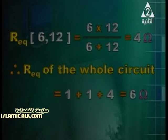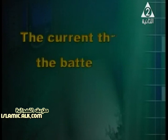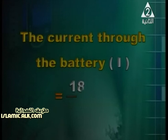And now we want to calculate the current through the battery. Current through the battery equals the battery 18 over the total resistance 6, it is 3 amperes. Potential difference across AB, across the first parallel group, is the current times R equivalent of this particular parallel combination. So it is 3 times 1, 3 volts.